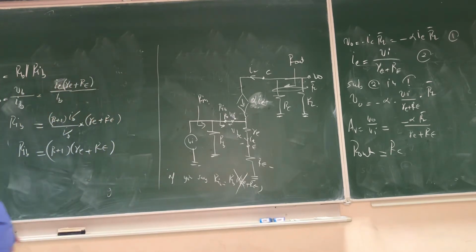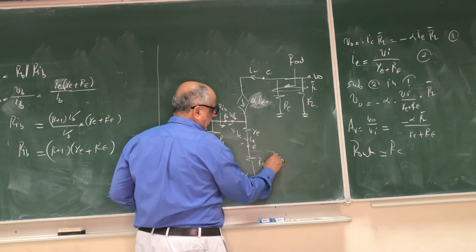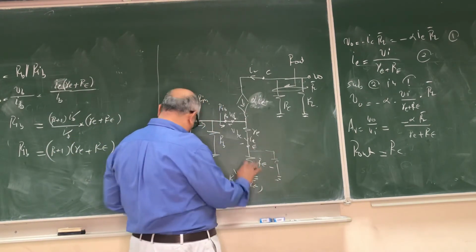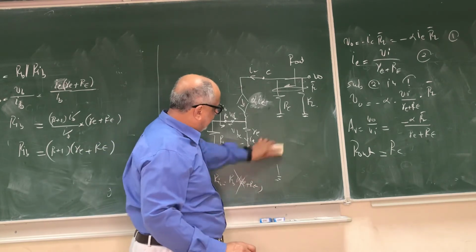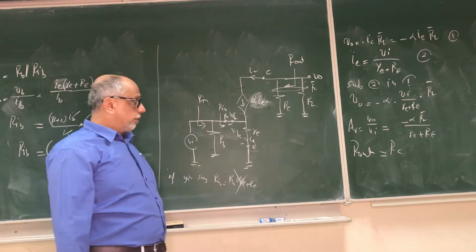So this is basically the common emitter amplifier configuration, where we have RE or we don't have RE. Now if we add the bypass capacitor, then it will short this. So in AC it is not there anymore, and we are coming back to the basic configuration.